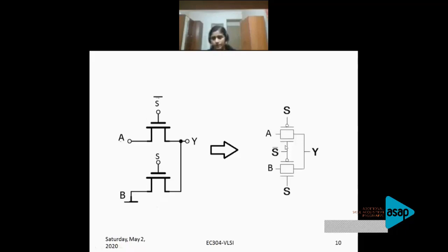So that circuit is here. Let's see whether we got it or not. This is the symbol of your transmission gate. What we had initially is simply an NMOS, so A into S bar, this part only we had. Now, in order to convert this pass transistor into a transmission gate circuit, you just have to add one more PMOS over this. So in this section, I added one more PMOS. That is the bubble that you have here.